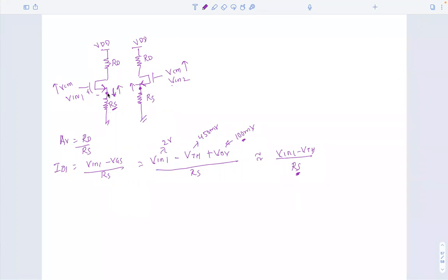Okay, so what I'm going to do is I'm going to short it. So when you short these drain terminals, what will be the ID current here, or the current that is flowing through these two terminals? 0. Yeah. This is because this is exactly at the same voltage, and this is also exactly at the same voltage. So the current here is 0. So it is kind of open circuit.